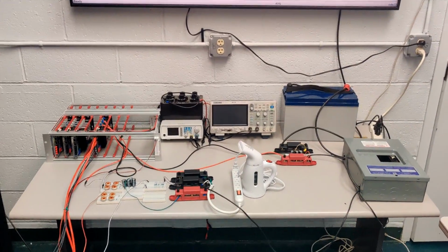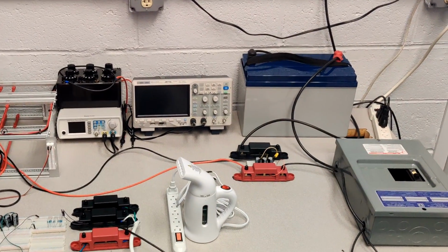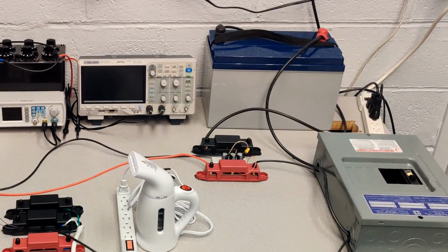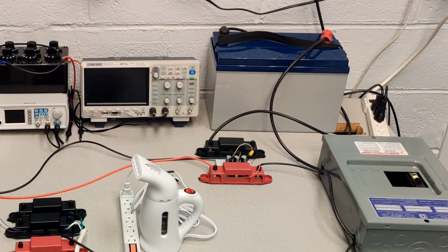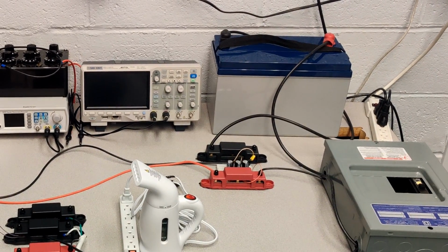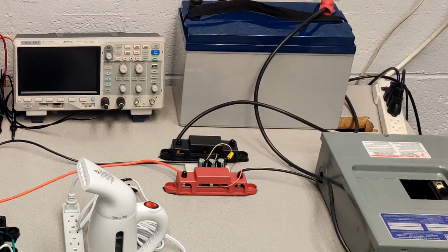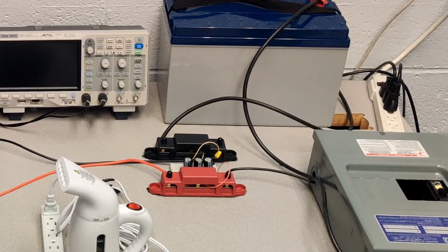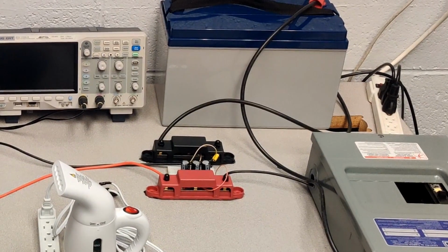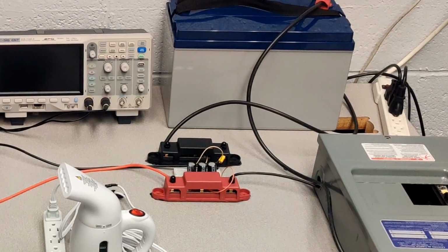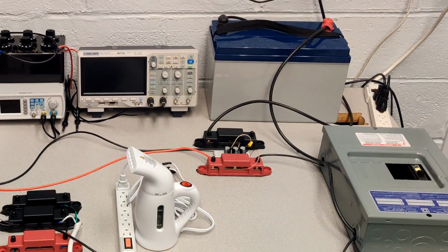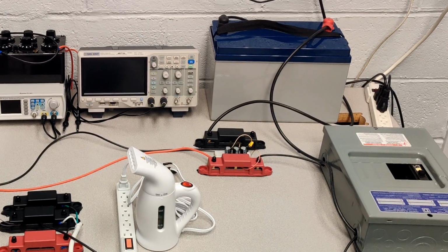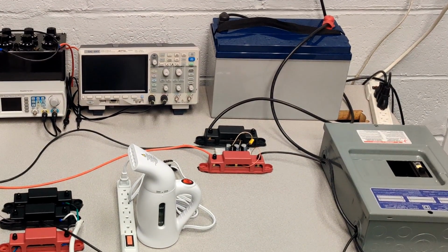In the hardware part, we installed a chemical battery. It connects to the DC bus through a controllable breaker. In the meantime, a set of capacitors are linked in parallel to filter the noise in the DC voltage. So, this section can be regarded as a voltage source in the short time scale.